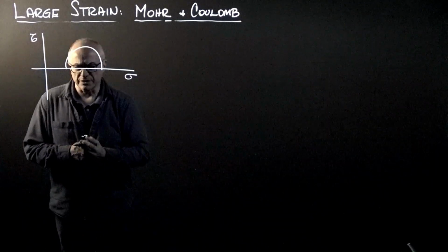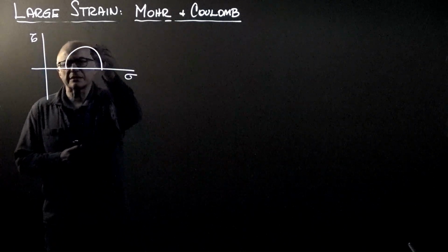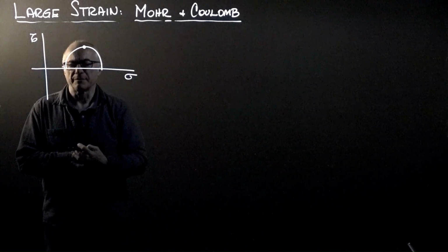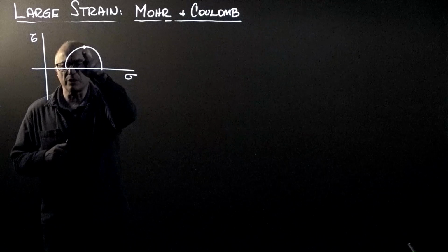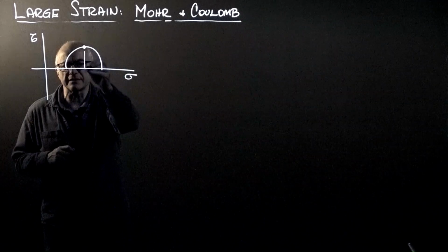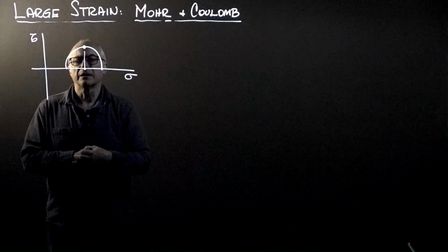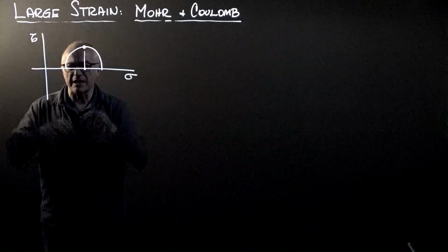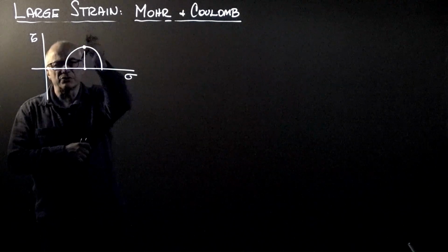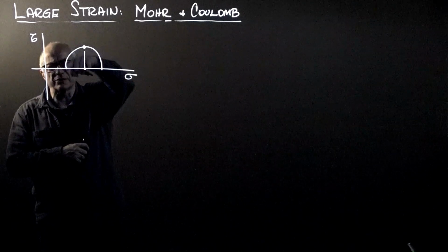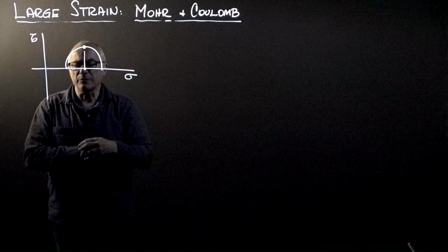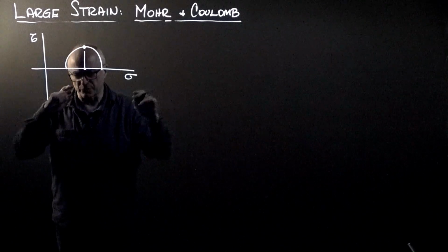The video on Mohr circles told us that the apex is all we need to know to define the Mohr circle, because out of the 3 points, we know the x and y position, and we know that the apex of the Mohr circle is always resting directly on top of the center, which rests on the tau equals 0 axis, in other words, on the sigma axis. Therefore, if we know the apex, we just draw a vertical line to the sigma axis, and we can draw the circle with the compass. This is very valuable because we don't need to draw circles anymore.